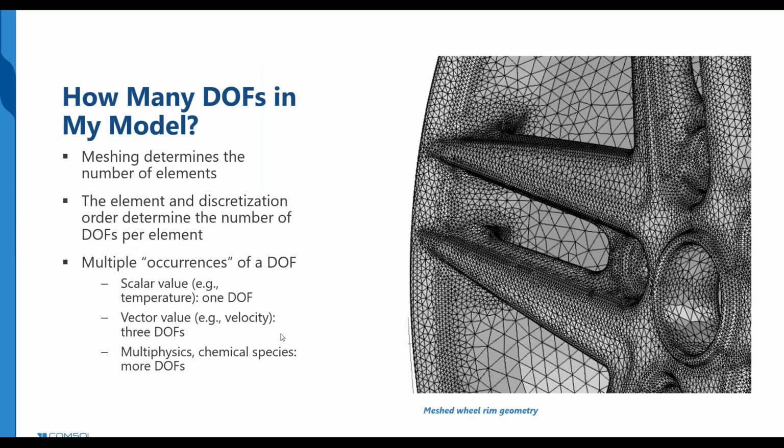That's just an example. So in an actual COMSOL model, how can I determine the size of the problem, the memory requirements? Yeah, that is not easy, but let's first at least start to figure out how large my model is in terms of degrees of freedom. As you might know, the number of mesh elements is important here, because the finite element method is using a discretization directly related to the mesh elements.